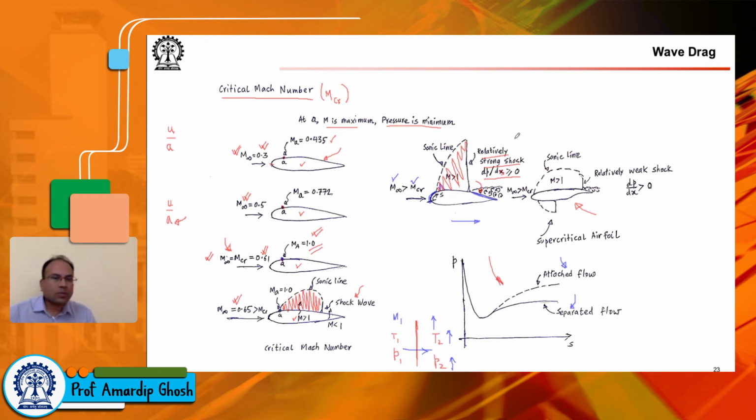What I'm trying to say is, we have a large shock wave creating adverse pressure gradient. We have flow separation. We have some situation like this. The reason for that is pressure drag due to flow separation. But what I'm trying to say is, this pressure in this region is actually exaggerated because of the compressibility effect, and we will see what that means.